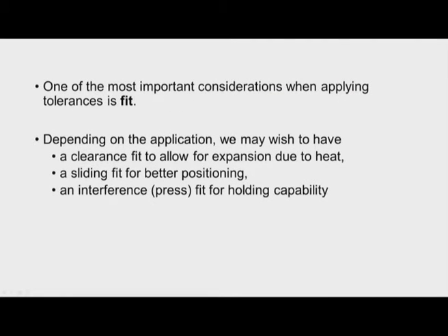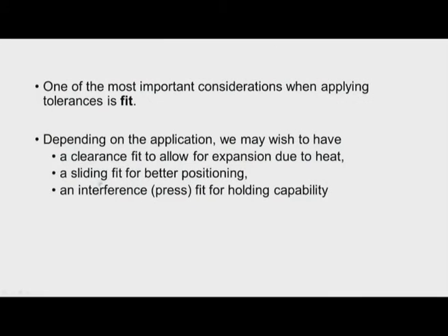Now depending upon the application, sometimes a clearance fit is also used to allow the expansion due to heat, due to continuous usage of the work part, for example a sliding shaft or a running shaft. There will be an increase in the temperature, because of that the shaft may expand, and if sufficient space is not available, it may get jammed in the hole. So to allow for expansion some clearance is allowed, and then a sliding fit is used for better positioning, and sometimes an interference fit is used for holding the parts together.